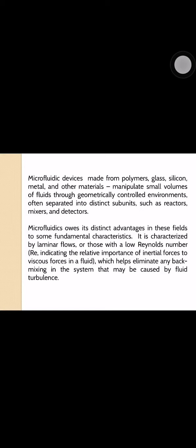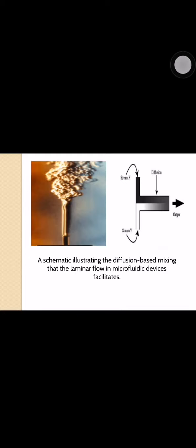It is characterized by laminar flow, or flow with a low Reynolds number, which indicates the relative importance of viscous forces to inertial forces in a fluid, which helps eliminate any backmixing in the system that may be caused by fluid turbulence, as shown in a schematic illustrating the diffusion based mixing that laminar flows in microfluidic devices facilitate.